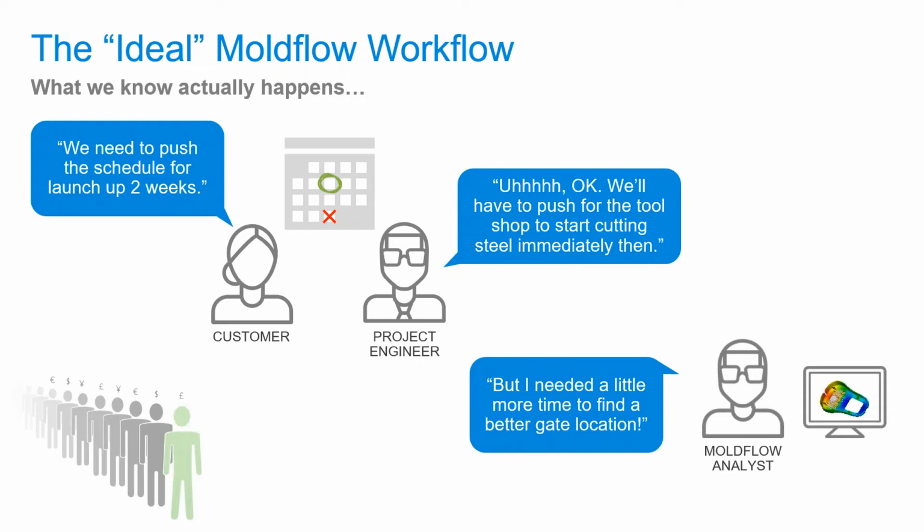On those legacy tools, and those tools that may have been fast-tracked through that design phase, this is where you may need to use Moldflow in a different way than the ideal workflow I just talked about. Using Moldflow in order to work backwards through the design of the part, tool, and process in order to address issues that you see within the parts your tools are already manufacturing.